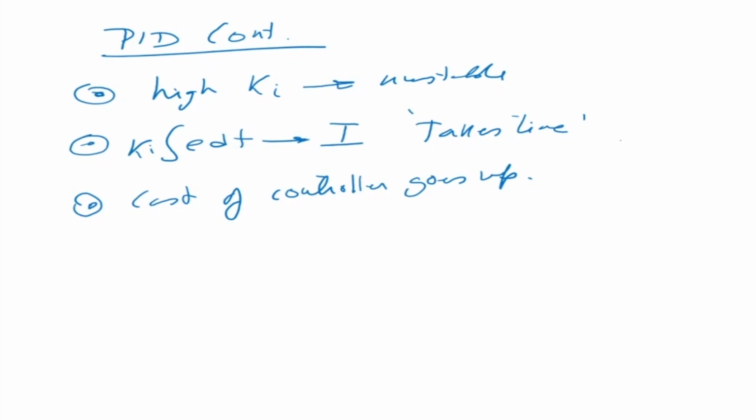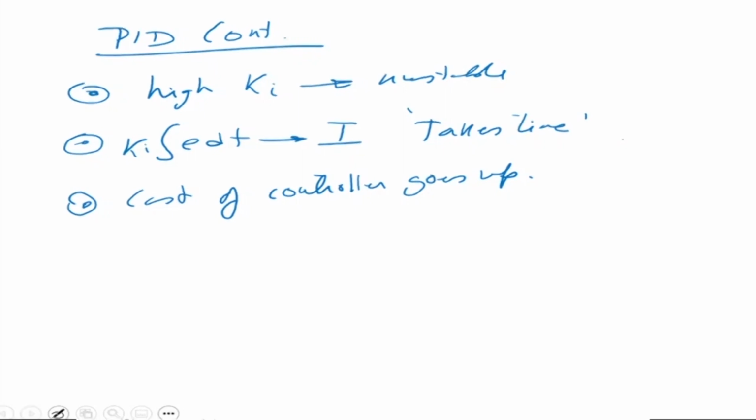So what we have seen in this lecture is how to control a robot joint using P control, PD control, and PID control. Now every joint has its own controller, and the moral of the story for this lecture is that a linear control system works reasonably well, because although there is dynamics, the dynamic torque is substantially reduced by the gear ratio.